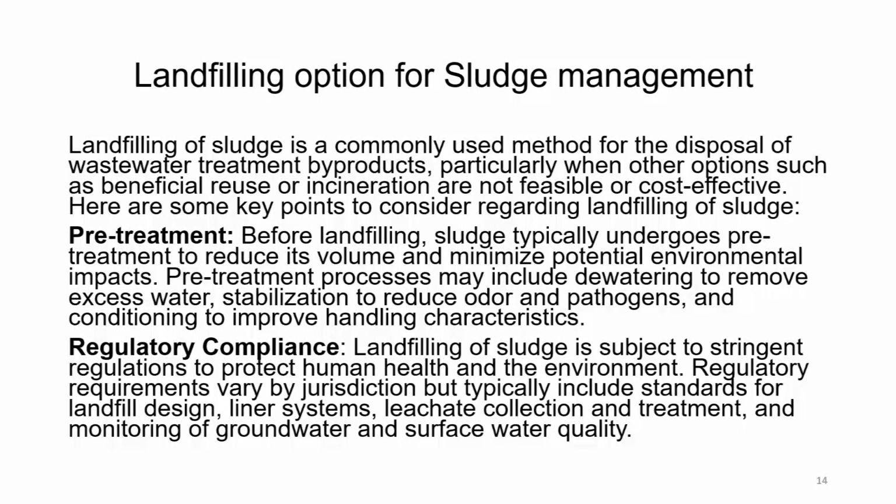Landfilling of sludge is subject to stringent regulation to protect human health and environment. Regulatory requirements vary by jurisdiction but typically include standards for landfill design, liner system, leachate collection and treatment, and monitoring of groundwater and surface water quality. So, a very concerted program is made for regulatory compliance of the landfill and sludge.